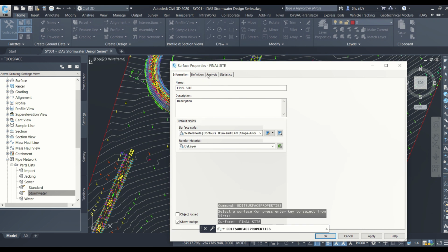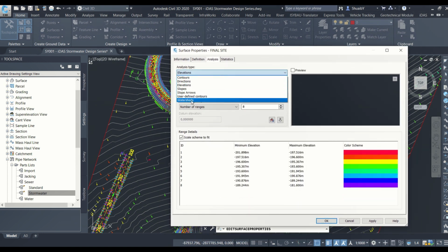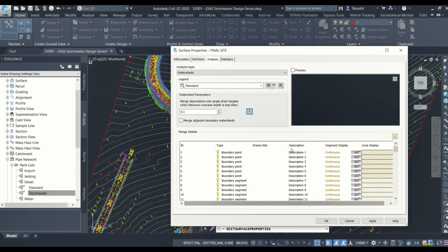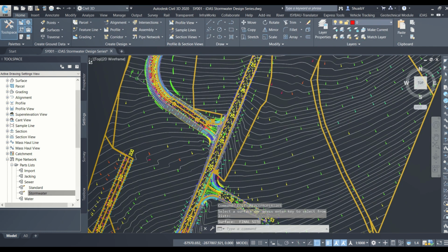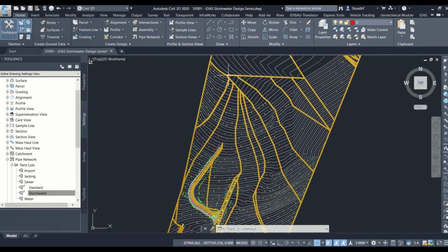So we're going to go to analysis and run the catchments. You see there is a watershed to generate the crest. We're going to make that 0.1, which is going to help us calculate it better. Hit OK, and here we are. We have calculated the effective areas, or the catchments rather, or the watersheds. Different words, same thing, more or less, right?